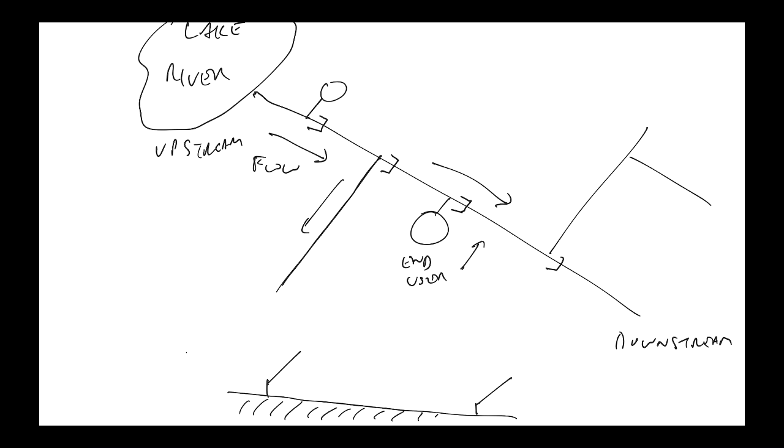Okay, and by adjusting the position of these regulating structures, you gain some authority over the flow downstream. Now, traditionally, these systems were operated manually. There was a human being that used to go up and down the channel, and it was as simple as pulling drop bars out of the channels, or putting them in to regulate the flow. So the opportunity for taking control action was very limited. It maybe happened once a day.